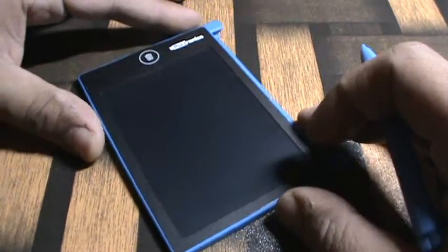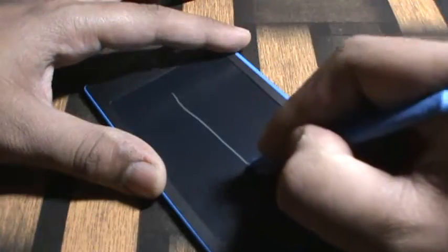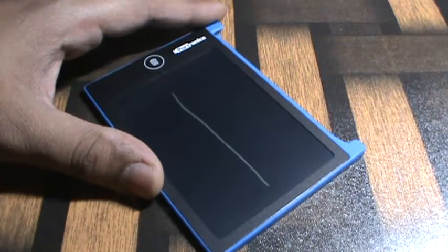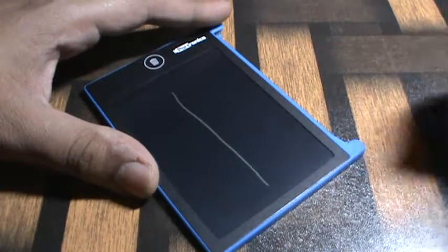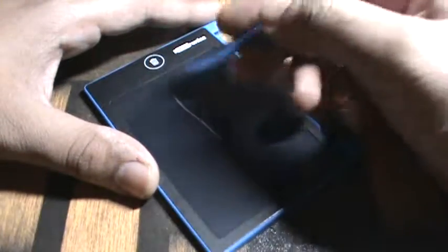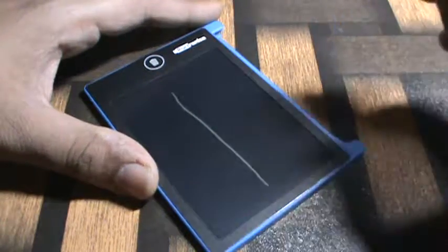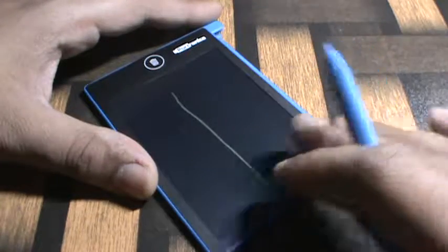So this is how a CPU looks when you consider everything. There's going to be a bus. This is a bus. A line. No, it's not a line, it's an 8-bit number, so it's going to be a set of 8 wires going in a straight line. If it's a 32-bit computer, it's going to be a set of 32 lines, or 64 lines.